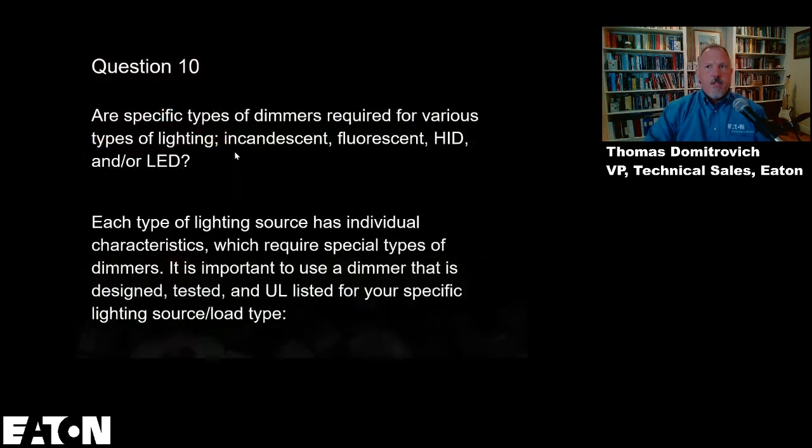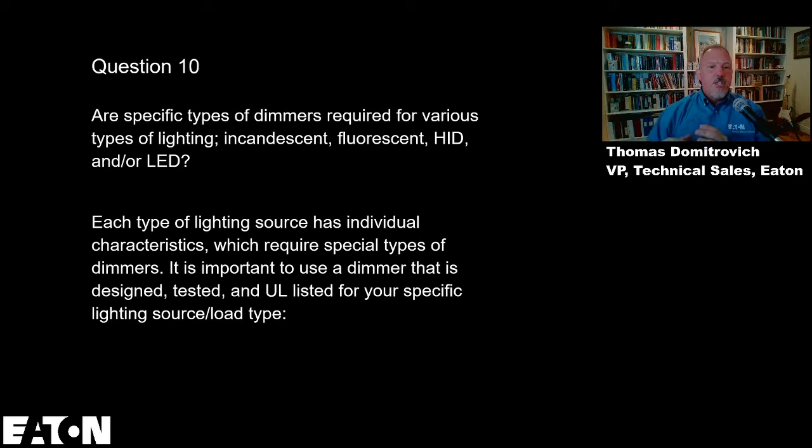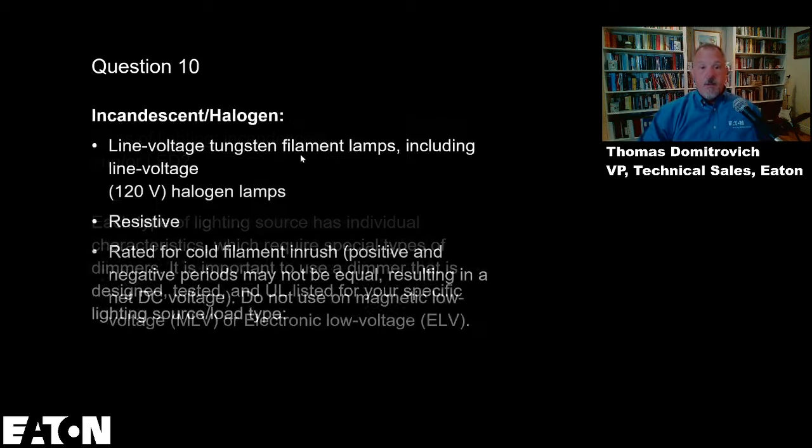We saw a little bit of this already. We had a little bit around this discussion. I would say each type of those lighting sources, we talked a little bit about from an inrush current and from a power factor perspective. We know that each of these types of lighting will have different characteristics from a load profile perspective. So it's important that we use the right technologies to turn them on and off, especially if there's specific listing requirements or specific labeling around the products themselves.